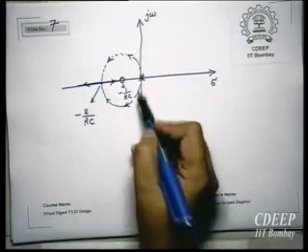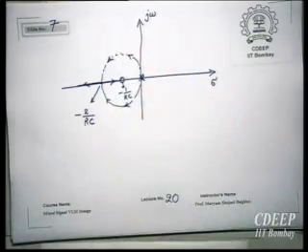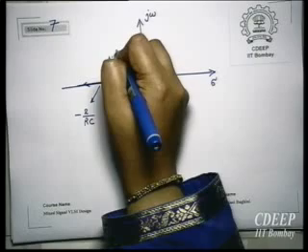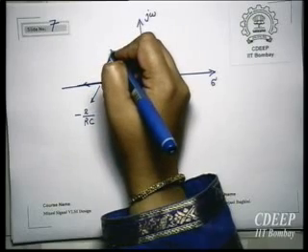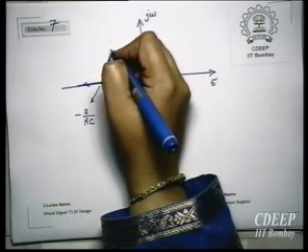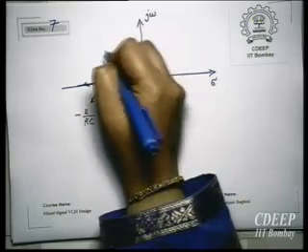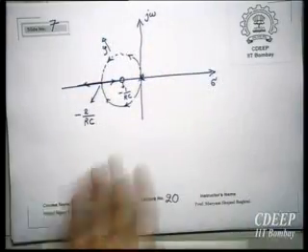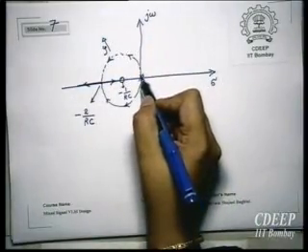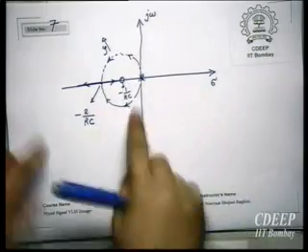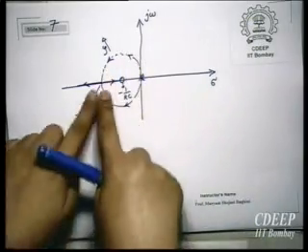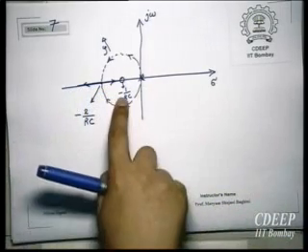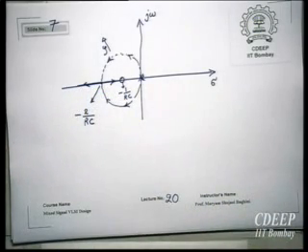So we will have 2 imaginary poles. This is the direction in which we increase the gain. This is the direction in which zeta increases. Zeta is minimum here and then it increases. Therefore, the poles are at the beginning imaginary and then they will be real. This is the zero, which is minus 1 upon RC.